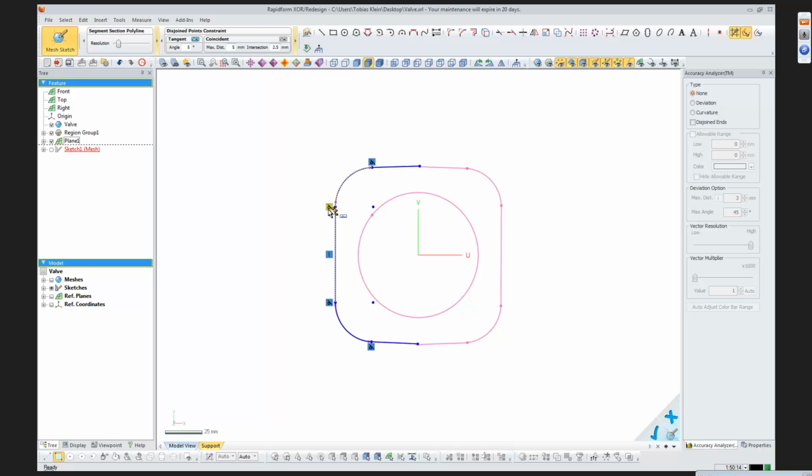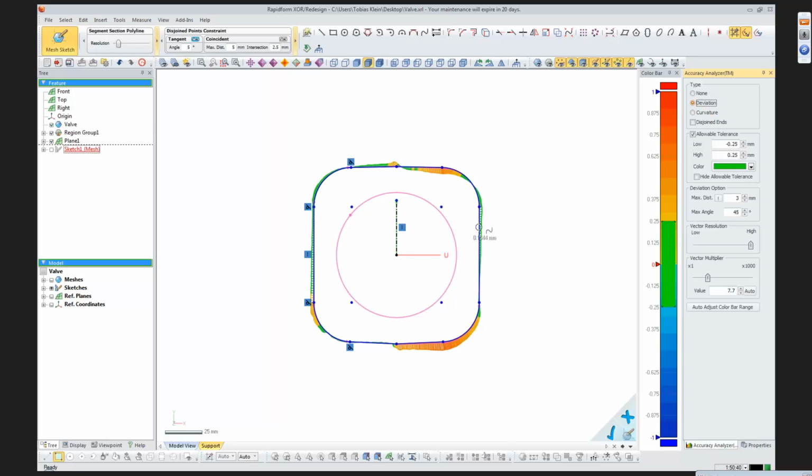Let's say we pick that sketch chain which is created, and it's automatically creating a vertical constraint, and it's automatically creating coincidences and tangencies, and you can then create a construction line, for example, from the middle, and over this construction line you could mirror this area, and then you could connect the endpoints, and so you get also your symmetric constraint.